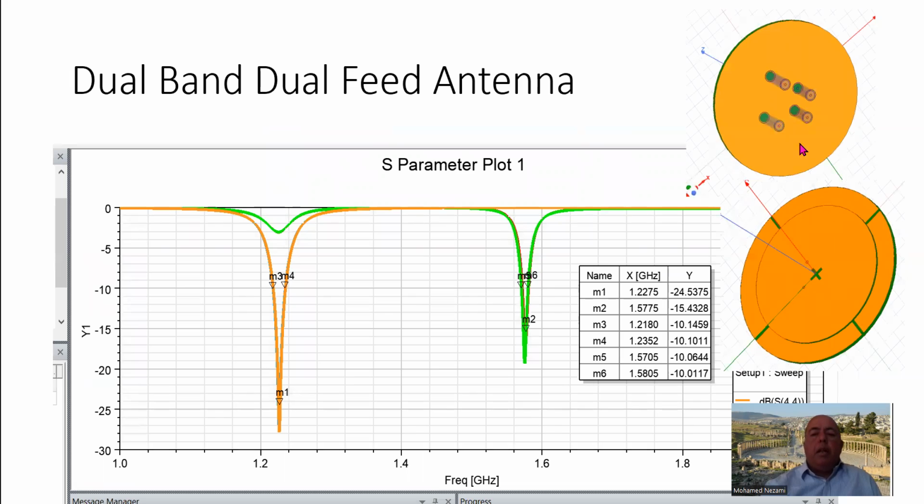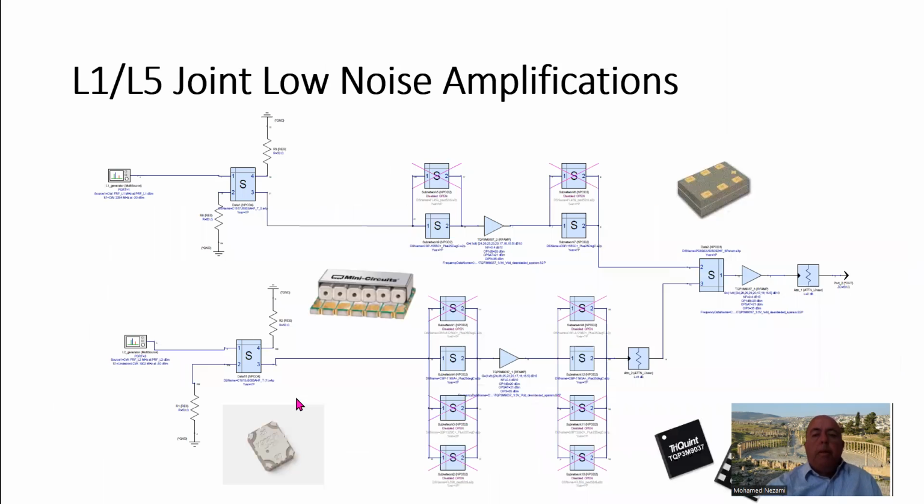So this is the antenna that I've used. Basically, it's a dual stack printed circuit board. It's not ceramic. Now, this antenna was designed using Arlon material, and I believe it's a 64 mil height substrate, and I chose to design it so that I could design the LNA on the back of this antenna, so that it's the same board.